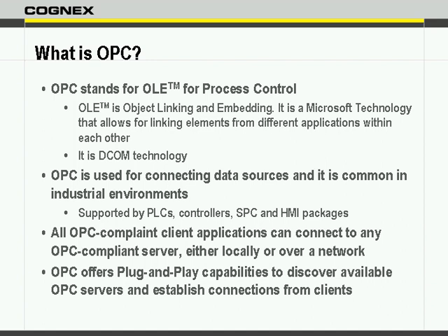As long as there is an OPC compliant server, you can share that information with any OPC compliant client, either locally or over a network. And this way, OPC offers plug-and-play capabilities.